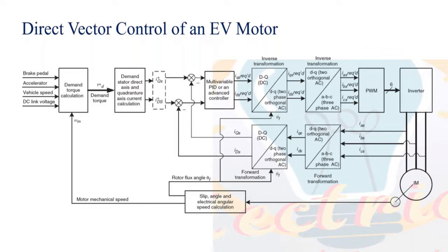You should know. So here I am using some mathematical transformations in order to determine the right amount of current I have to supply to the motor for the demanded torque. The first task is the forward Clarke transformation. I am typing that in the chat box also for your understanding: forward Clarke, C-L-A-R-K-E. The forward Clarke transformation is used initially.